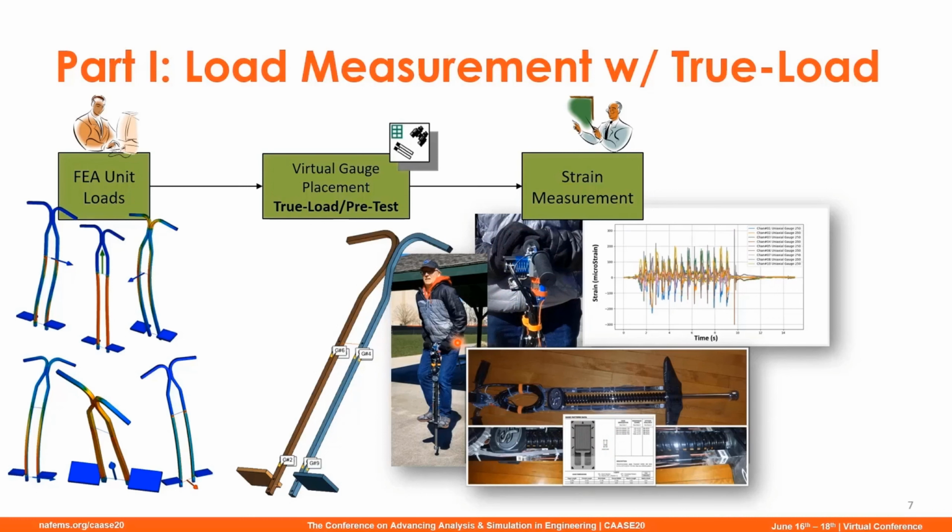We've basically got a little data acquisition system that we're driving these strain signals into. Then I went off and collected strain data on the pogo stick, just using the pogo stick here. From this event, we now have time histories of strain data for our 10 channels of strain. Okay. So this is us measuring the strain. The whole idea is that we want to take this measured strain and turn that into load, and we're going to do that with the post-test software.